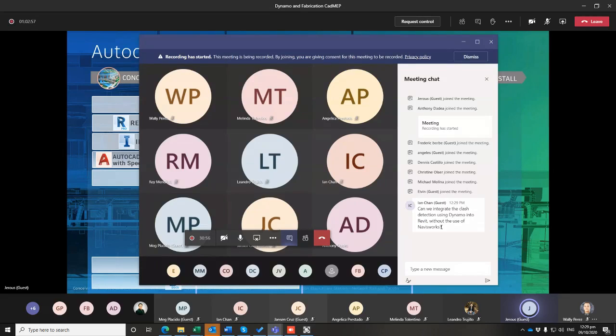I don't think so. Basically, you can run the initial interference checker of Revit with Dynamo. That will work for hard clashes only. But since Revit has no capability in terms of clearance tests, those clearances won't be acknowledged. But I think you can run an interference check in Revit. Well, I'm not really sure, but we have to look for the proper nodes that can do that.